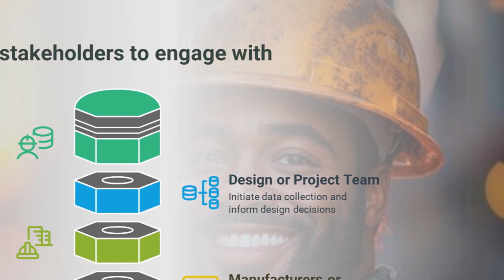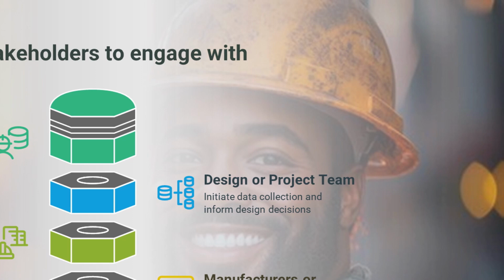The design or project team is likely to be responsible for initiating the process of collecting materials passports. They may use existing passports to inform design decisions based on the data available or set out the specification requirement and the data that needs to be collected in alignment with the developer's passport strategy.